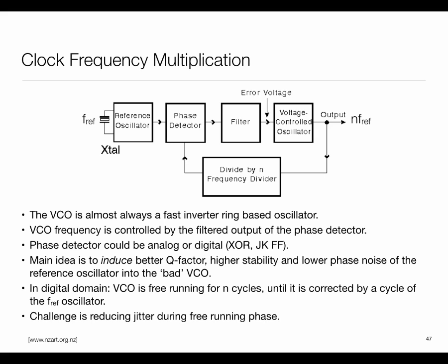We have a circuitry which detects the phase difference between a signal out here and a signal out here. Essentially, it asks whether I have an identical signal here and here or not. This error we smooth out, and feed into a voltage controlled oscillator, an oscillator whose frequency can be affected by changing the voltage.